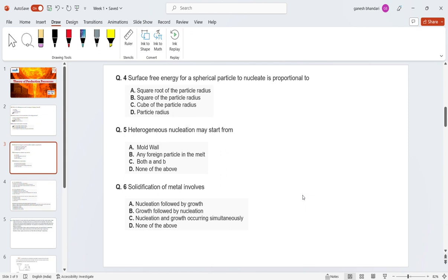So as the wettability becomes higher, your solder will spread more on the surface. That's what we want at the time of soldering. Your wettability should be higher. As your wettability is higher, it will spread more, and that's why you will get proper soldering.